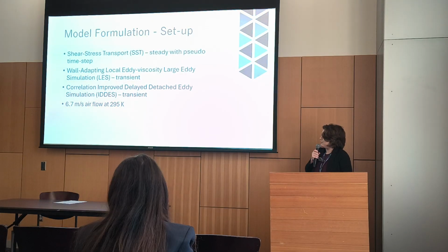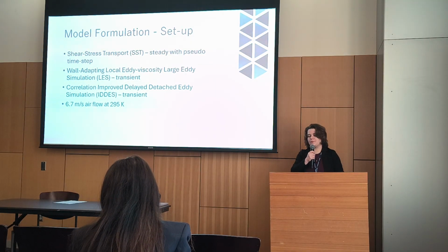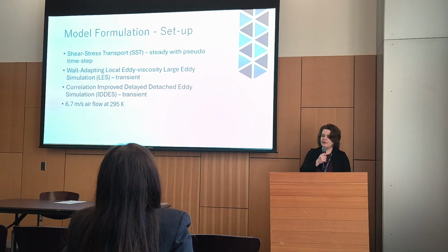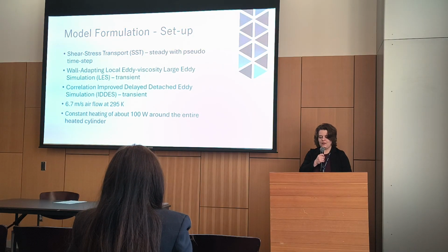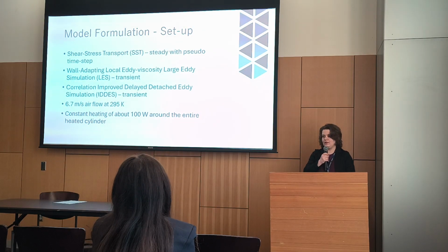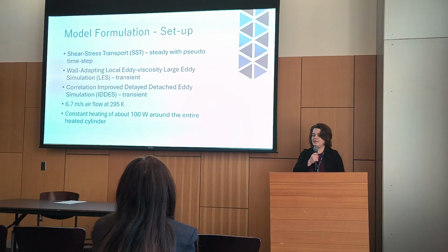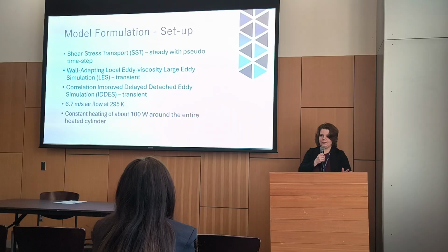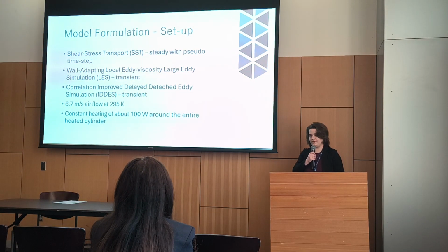So the actual parameters: it was a 6.7 meters per second airflow at 295 Kelvin, and then a constant heating of about 100 watts around the entire heated cylinder. This gives us a Reynolds number of 1170 based on the diameter, which is enough to be considered turbulent.